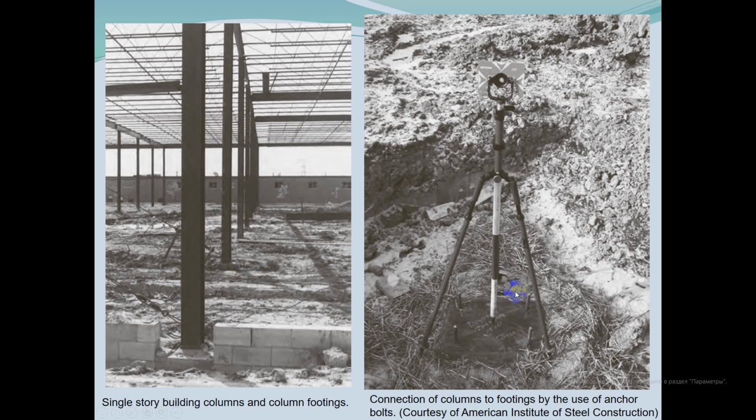This is a connection of column to footing by use of anchor bolts. A template can be used to properly align the bolt pattern to the column center line.